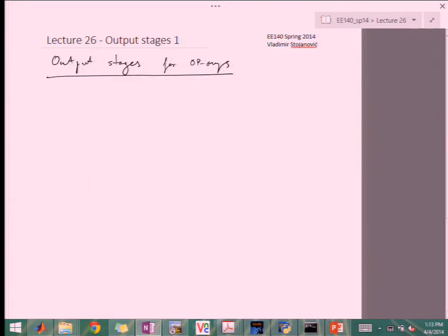When we talk about just the output stage, it's a little bit different set of requirements than on all the gain stages that we were looking at so far in an op-amp, where we were adding stages to add gain, and the goal was to boost the output impedance so your gain can be larger. Here, actually, it's quite the opposite. One of the first requirements is to deliver specified power to our load without distortion.